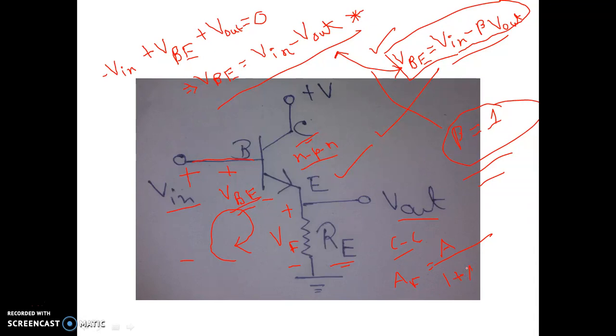and you know the formula for overall gain of negative feedback, that is AF equal to A by 1 plus A beta. Okay, here A is the basic amplifier gain and beta is the gain of the feedback network, and AF is the overall gain with application of the negative feedback scheme. Now suppose A beta is very much greater than 1, so obviously we can ignore the term 1 with respect to A beta and we get AF equal to A by A beta, and A and A cancel each other. So basically what we can get, AF equal to 1 by beta.